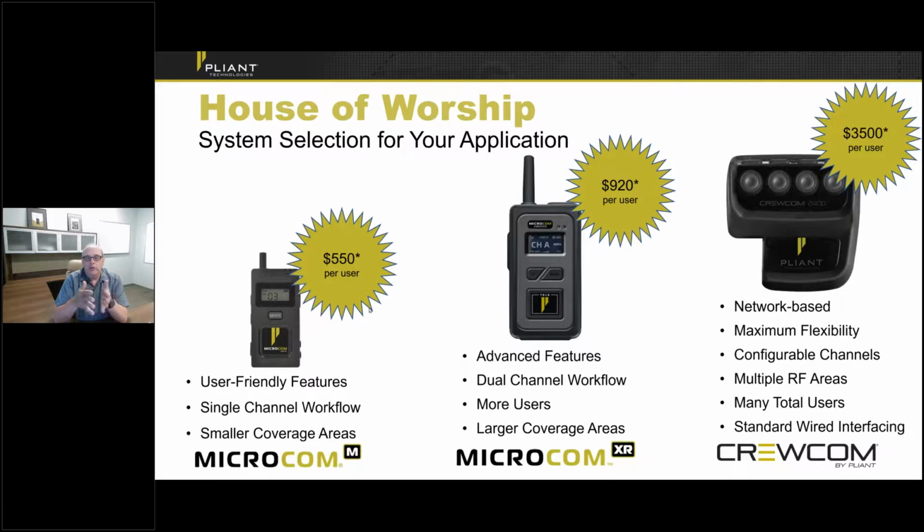Other things to consider when looking at the three systems is range. Mark showed you some of the average ranges that we get, and I'll show you some facilities and talk a little bit more about range. In the US, we do sell a 900 megahertz product, which is not in the same band as the majority of wireless microphone products. Those are typically UHF based, so you don't have to worry about coordinating frequencies with wireless mics. Outside of the US, 2.4 is the go-to, and same thing there. I just have to be considerate of the fact that it is using the same band as Wi-Fi, but it's not a Wi-Fi product. So those are some of the considerations.